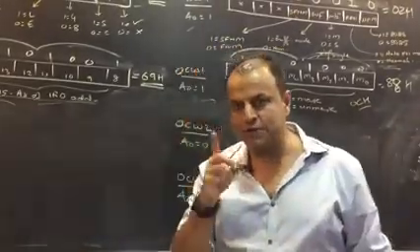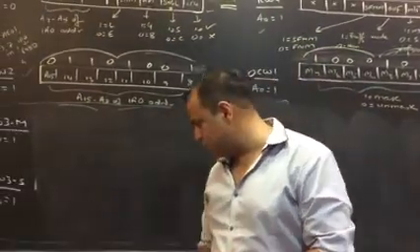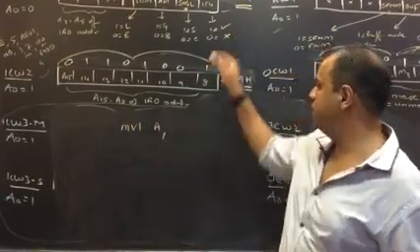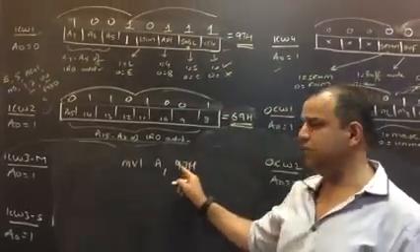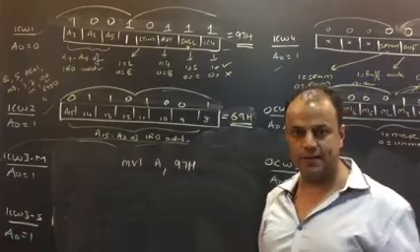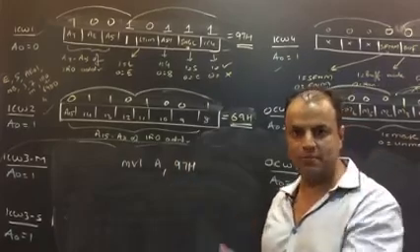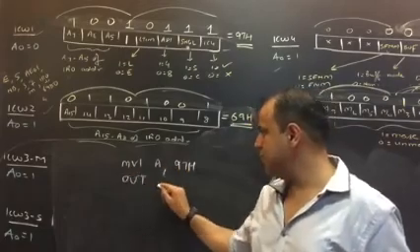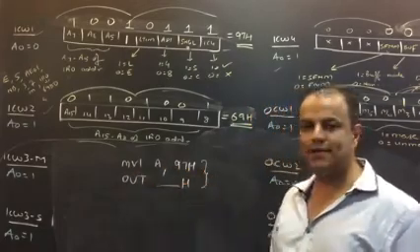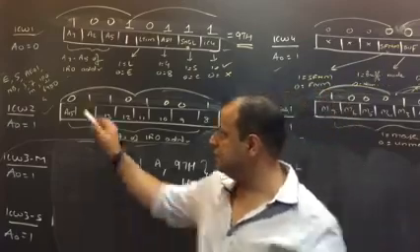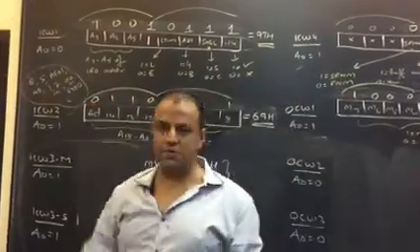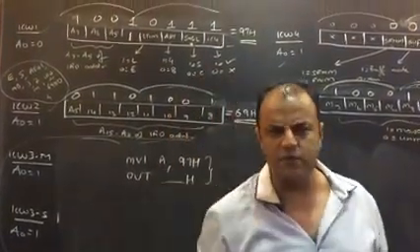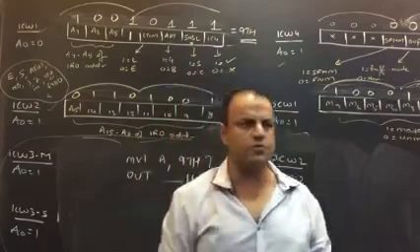In and out instructions work only on the A register. So this is how your program will be. MVI A, 97H. Put the command value as data in the A register. What is a command? It's data. It's a number that you'll be sending. So put that 97H in the A register and do an out at the address of 8259. That address, either in the specifications of the question they would have written, assume 8259 has so and so address, or many a times they don't write it, you choose your own address, whatever address you want.